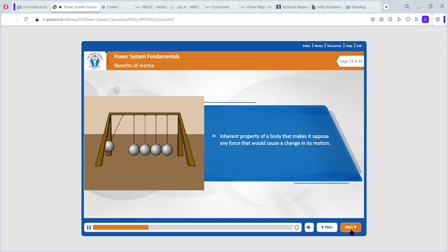If there is a sudden change in system frequency, these parts will carry on spinning even if the generator itself has lost power and slow down that change, what we call the rate of change of frequency, while our control room restores balance. Grid inertia is a form of energy storage which addresses imbalances between supply and demand on electricity grids over very short time periods, typically on the order of fractions of a second to several seconds.